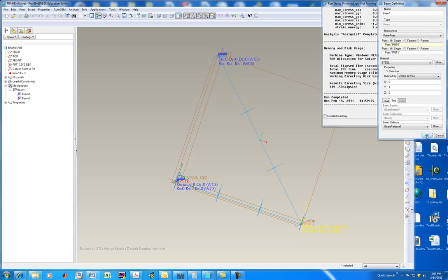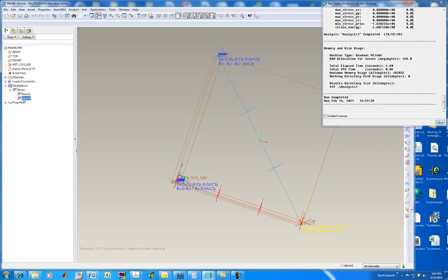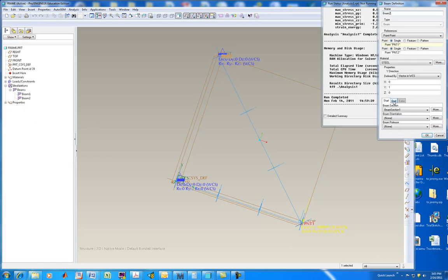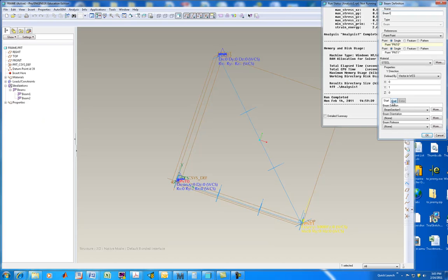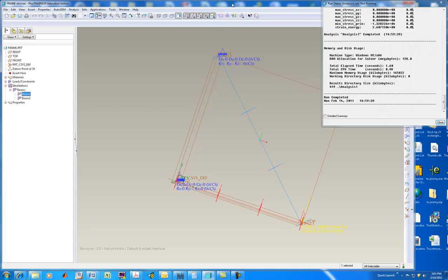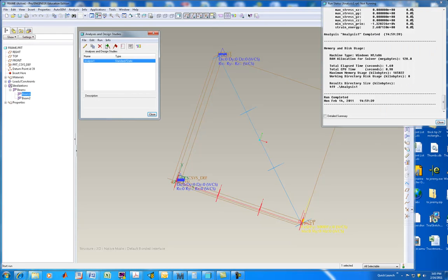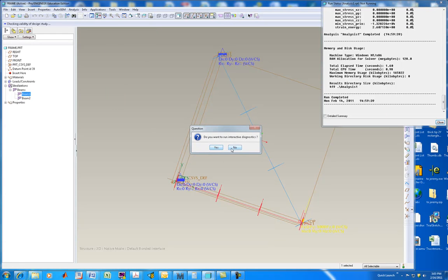I'm going to turn on that release. Good. Beam 2 is the upper one. I'm going to remove the releases from beam 2. I had the beam release in the wrong place. Bear with me on this, but it's a mistake you might make as well. So beam 1, the bottom one, let's just check it one more time, has a release at its far end. Okay, this thing ought to run differently now and show the result. Run it. Yes. No.